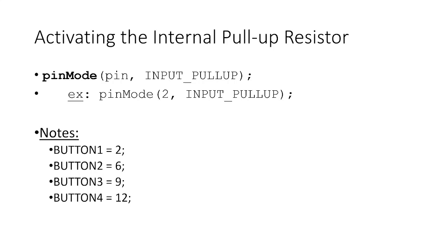We're going to say pinMode. So you must be keen. So pinMode button, comma, okay, it's input, but because we don't have the pull-up resistor physically in our circuit, we are just going to use INPUT_PULLUP. Then pinMode, then LED. It must be case sensitive. So if I write LED like this, I think I'm going to get some error.